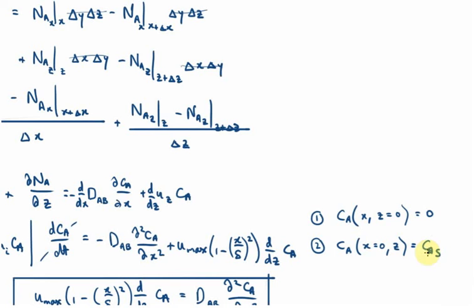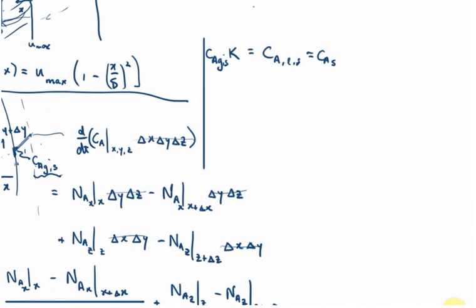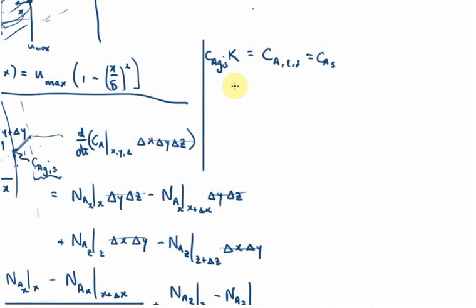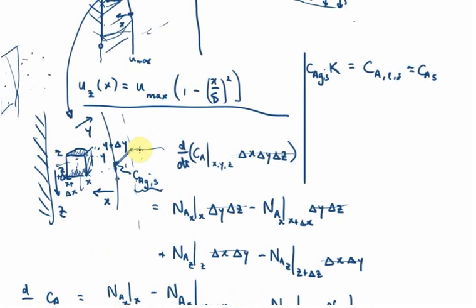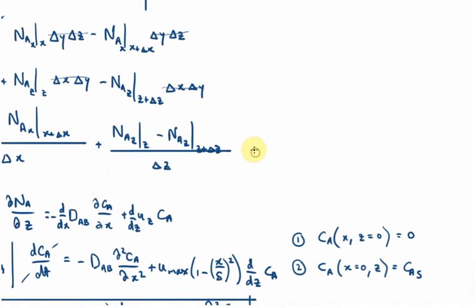Right, so there might be a little bit of work behind trying to find this value, but in principle we can do it. We can look up equilibrium constants, and we can work out mass transfer coefficients, and we can translate a bulk gas concentration into a surface concentration, and then through the equilibrium estimate the concentration in the liquid right next to that gas. So we can somehow get a number like that. It's not that difficult. Once we have that number, then that boundary condition is fully specified.